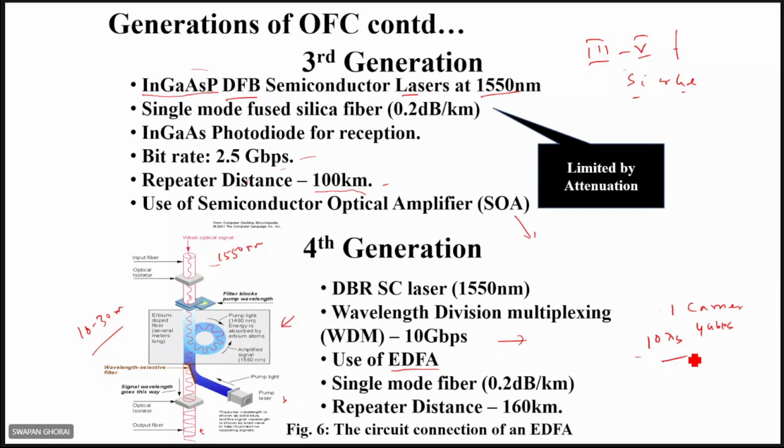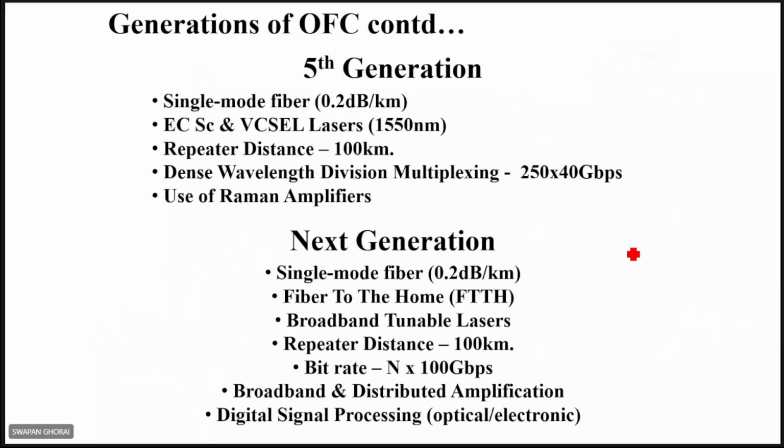The same fiber can support all those things. So that is the WDM system. And for dense wavelength systems, more than 100 such wavelengths can be transmitted. You see it here, dense wavelength multiplexing is shown here. So you can have huge capacity in DWDM systems, right?